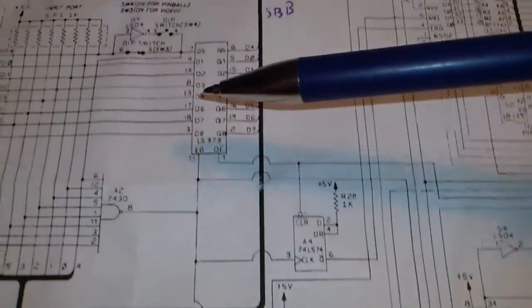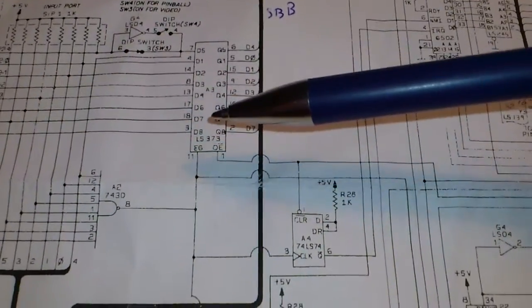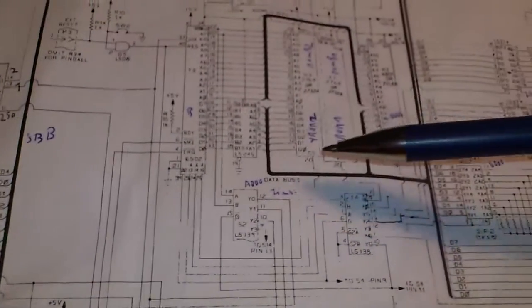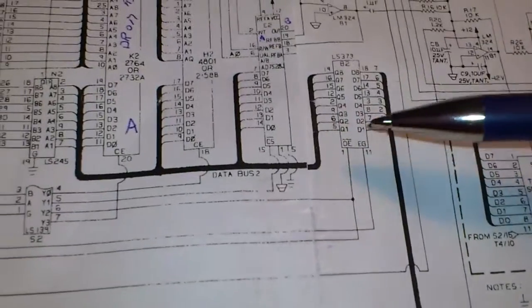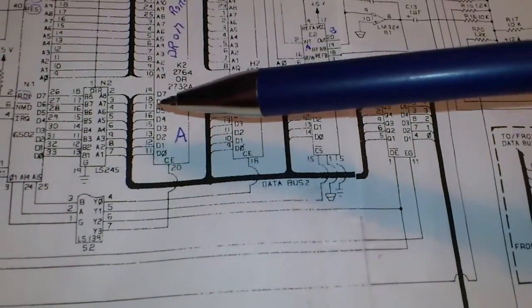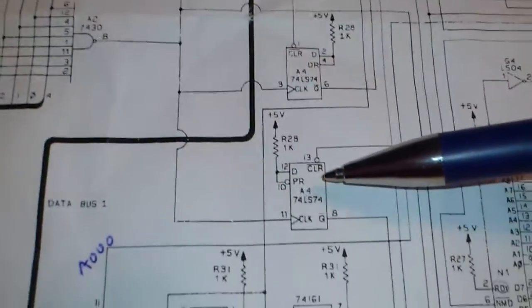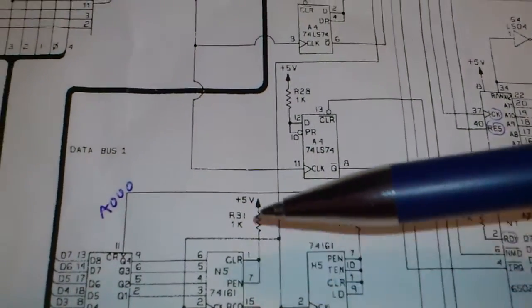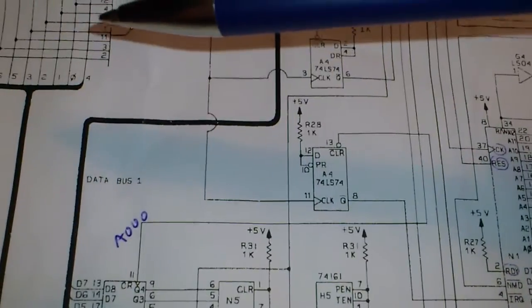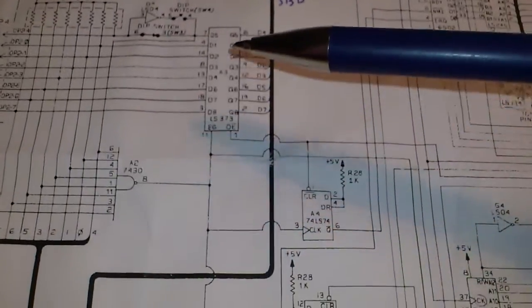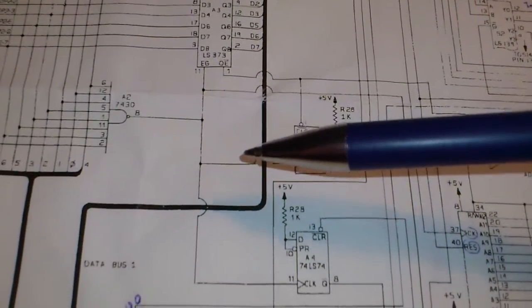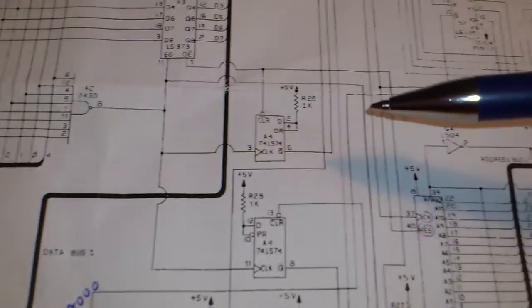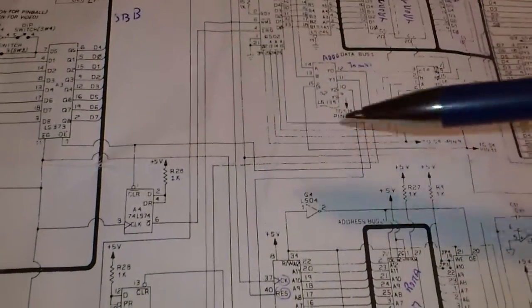As you can see, this latch here corresponds to the upper CPU, and there is another latch here which corresponds to the second CPU, the lower CPU. They both have their interrupt D flip-flops here, that's for the upper one, that's for the lower one. So once again, if there is a new sound code coming in, the sound code is latched here, and at the same time this D flip-flop is clocked and the interrupt line is pulled low for both of them.